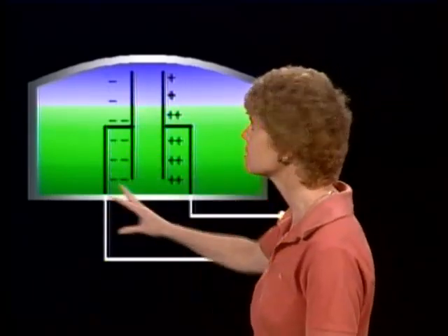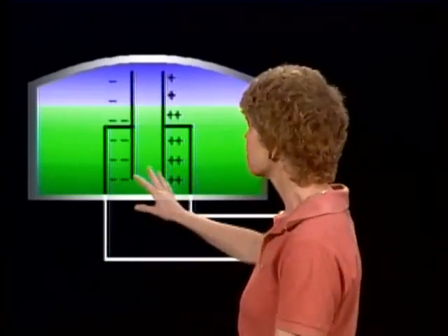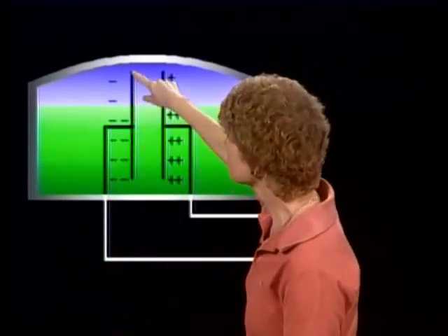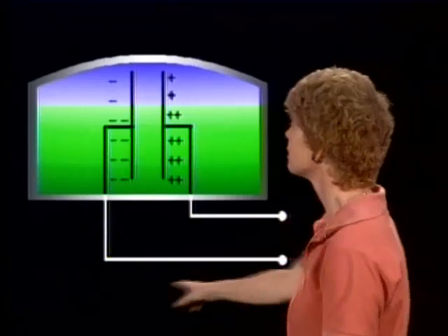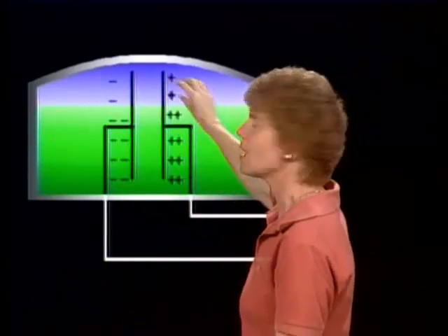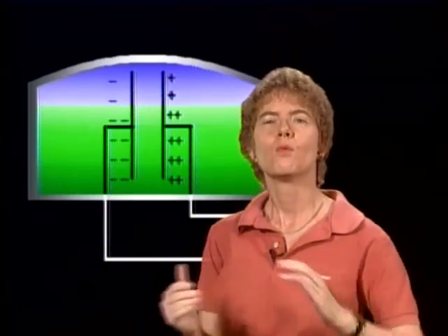In the tank, there are no moving parts as far as a capacitance type or electronic fuel quantity system is concerned. What you've got is a probe, or maybe several probes, that are installed in the fuel tank. This is the probe here, and here are the electrical wires that are coming out of it. We have fuel in most of the tank, but then we have air up above it. The probe or the tank transmitter basically is an electric capacitor. It's got fuel and air located above the fuel, which act as a dielectric. Now, a dielectric means a non-conducting material.